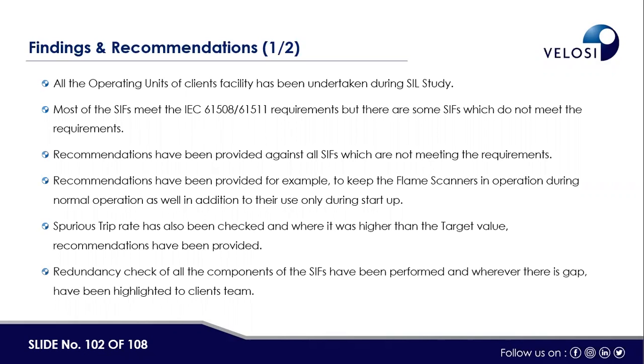For example, all the operating units of the client facility have been undertaken during the SIL study. Most of the SIFs meet IEC 61508 and 61511 requirements, but there are some SIFs which do not meet the requirements as well. Recommendations have been provided against all SIFs which are not meeting the requirements. For example, to keep the flame scanners in operation during normal operation, in addition to their use only during startup activity. Spurious trip rate has also been checked, and where it was higher than the target value, recommendations have been provided.